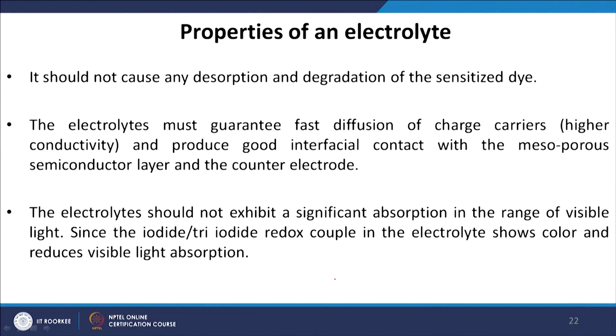The electrolyte must guarantee fast diffusion of the charge carriers or higher conductivity and produce good interfacial contact with the mesoporous semiconductor layer and the counter electrode. So, now these electrolytes are there at the interface of the TiO2 layer and also at the platinum counter electrode. Now, their interfacial stability or the interfacial properties with the TiO2 layer and the platinum counter electrode should be very good, and at the same time they should express a very fast diffusion of the charge carrier. That means their ionic conductivity should be very high.